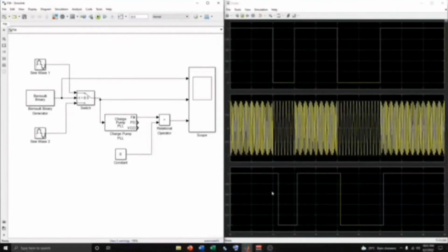But the difference we can see is in the shape of the modulating signal, here and here. The gap between the lines of the waveform is different. In short, there is no gap when the digital input is 1. At the column where the digital input is 1, there is no gap between the lines of the waveform signal. And when the digital input is 0, there is a gap between the lines of the signal. This we call space frequency. When the digital input is 0, there is space frequency. But when the digital input is 1, it is called mark frequency.